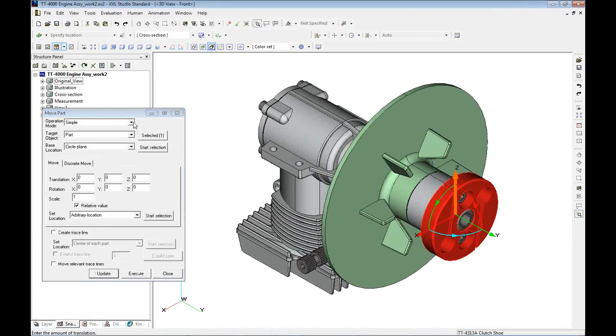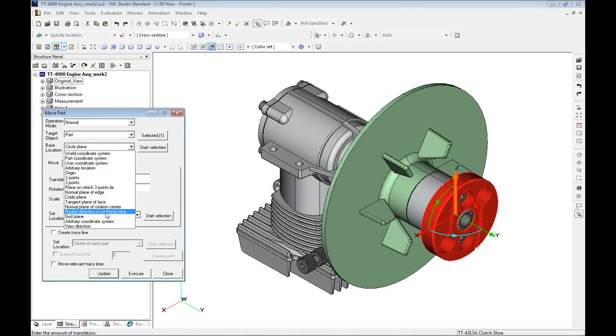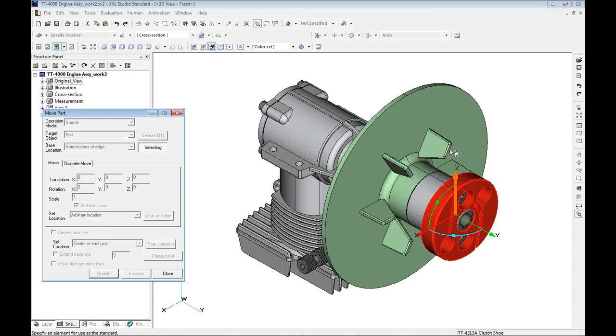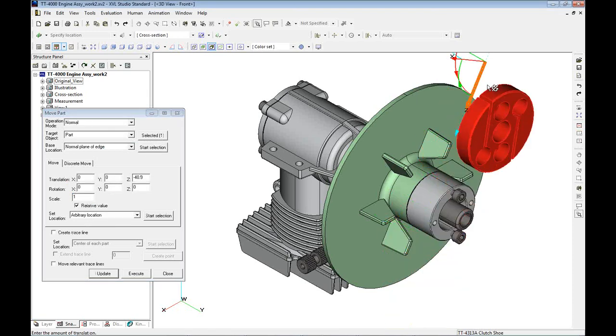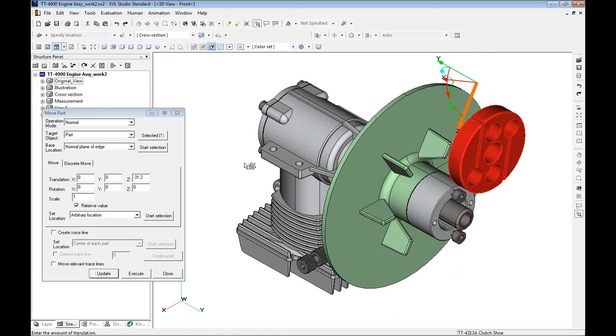But yeah, once you pick on a part, you have the ability to actually go in and set up the coordinate axis. So you see, you have a lot of options here to choose. You can go normal to a plane, normal to a surface. You can set up 3 points to make a plane. You can choose cylinders or circles. So you have a lot of options there to set up arbitrary movement that's not standard with the current XYZ. So it's pretty easy to do. All right, good. I hope that answers the question. Yeah, I think that was great.